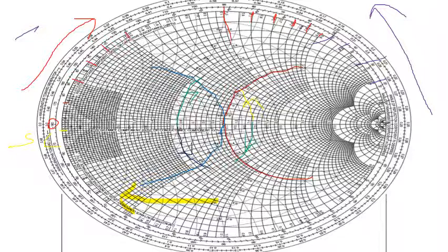Now how do you note the readings? Please note in a normal Smith chart, for solid arcs, the impedances are always positive in the upper half, whereas the impedances are negative, capacitive, in the lower half. It is capacitive in the lower half. Now when you are taking dotted, I am talking about the purple one, the upper half will always be negative.